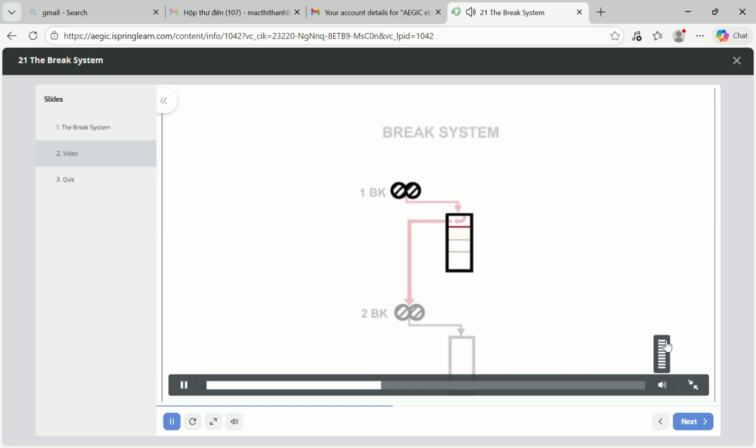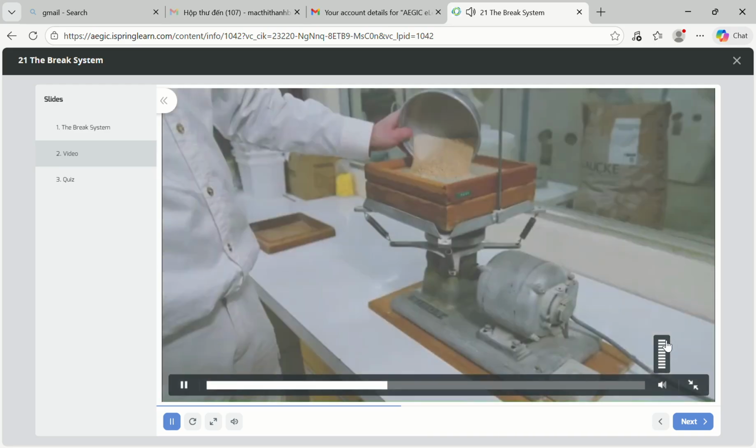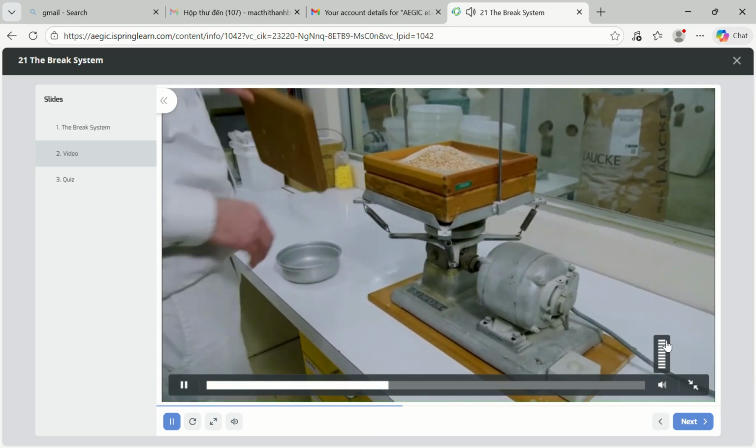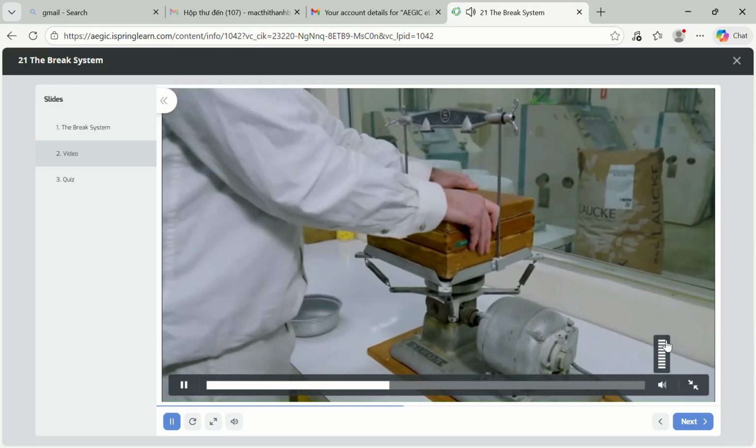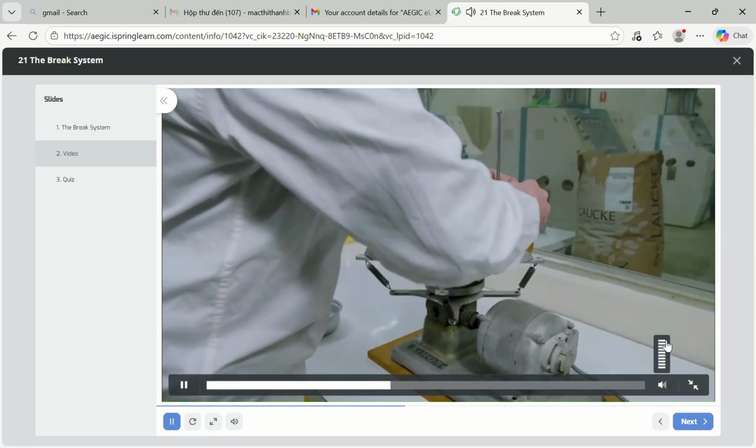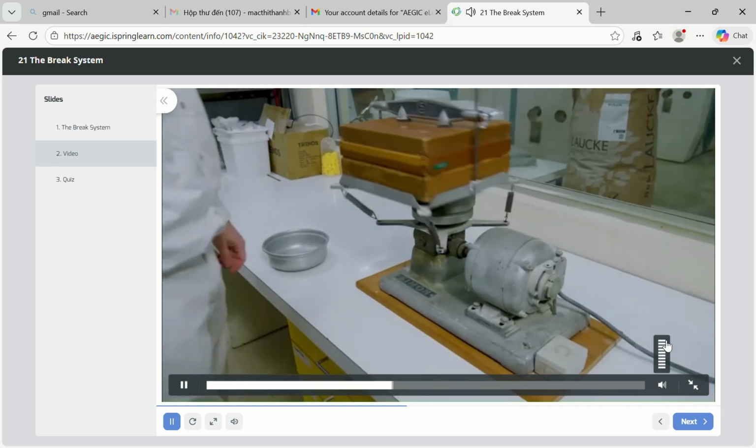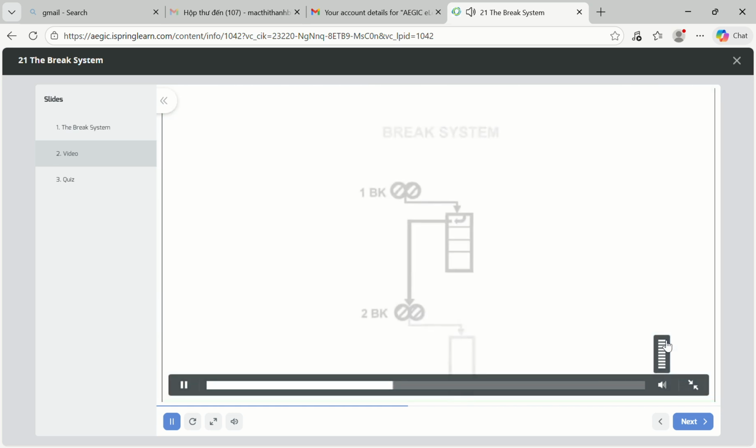The percentage of stock released through this screen is referred to as the release for that roll. So in this case it would be called first break release. The release in the plant sifter is usually approximated based on a sieve test on a lab sifter. The harder the stock is ground, the finer the stock becomes, and the more stock is released through the screen.